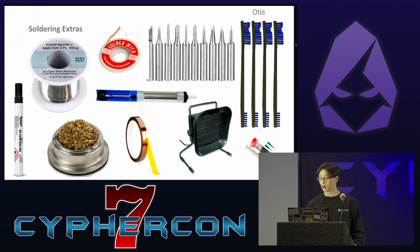Then finally, in the bottom right, or I guess second to finally, is some solder paste. When you're working with those surface mount components, you really might want to avoid using the iron for some of them. So with the solder paste, you can put daubs of the paste on all the pads you're trying to solder, put the chip or component you're soldering into those globs of paste, and then use the hot air rework station to melt them all down, and it'll kind of shift its way into place.